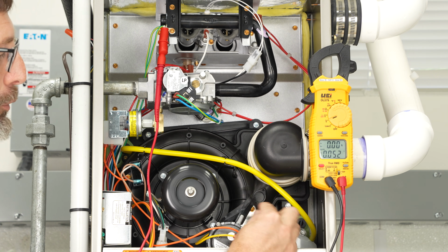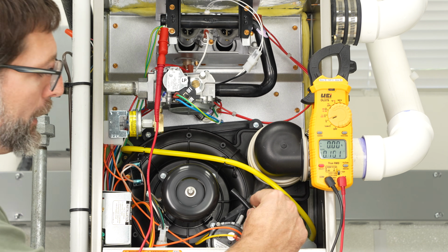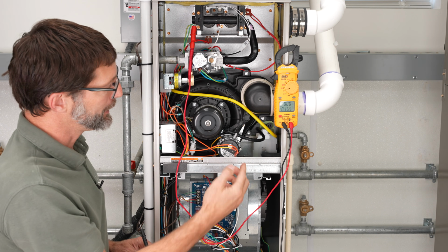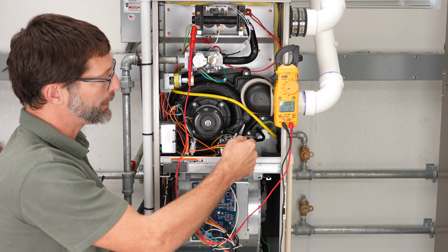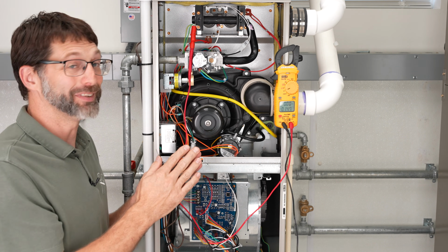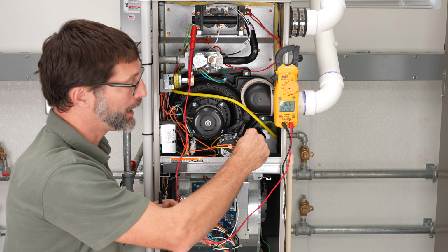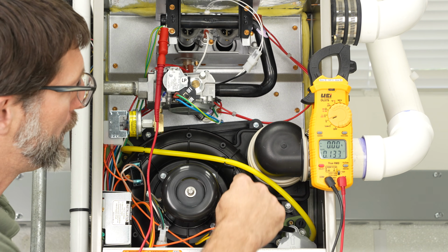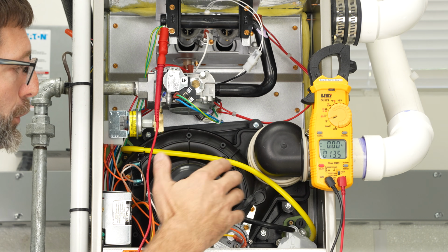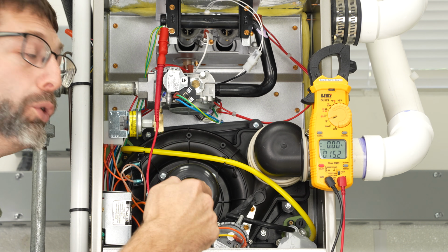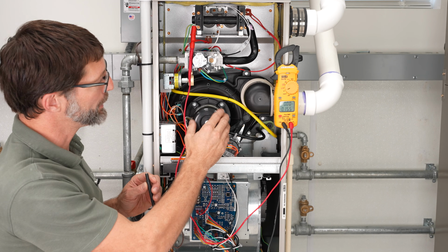And right now we know because we have this tube disconnected right here. And the issue could be that you have a tube problem. I've seen them decomposed basically. I've seen them blocked on the inside. I've also seen, if this has a metal inducer motor housing, the little hole is clogged. And so it could be corroded and clogged.